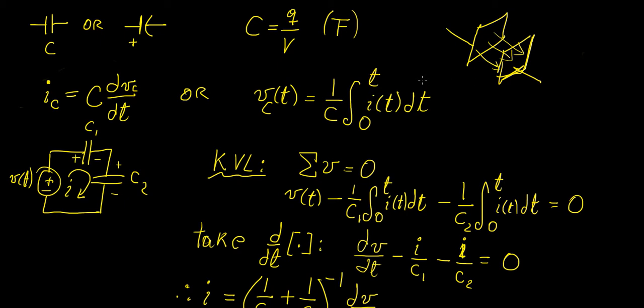In this course, we're only interested in how to use this for electronic circuits, so I'm not going to go into the physics of it. But the basic definition is capacitance is essentially the ratio of the amount of charge that you have and the potential difference. And then the next thing is going to be, this is usually measured in farads. But capacitance is usually quite small in the devices that you find. So I would say a more common unit would be microfarads or even nanofarads. And that's the kind of thing that you encounter in regular electronic circuits.